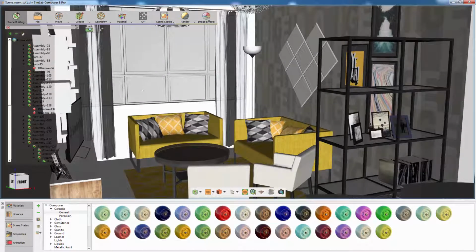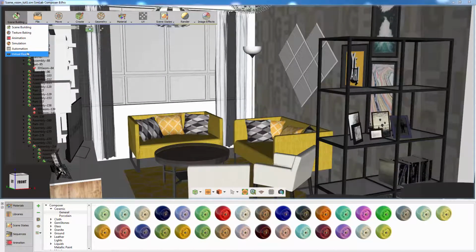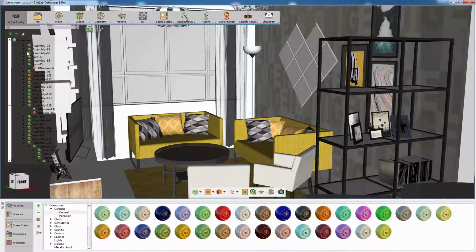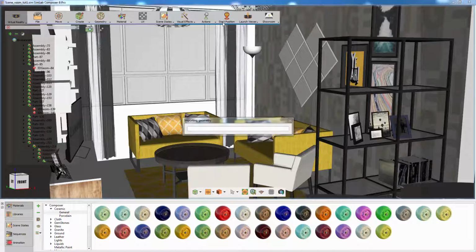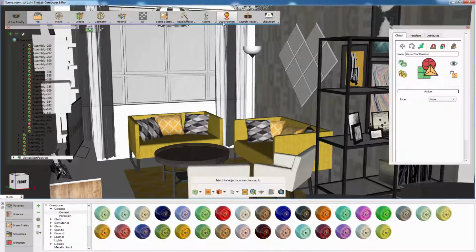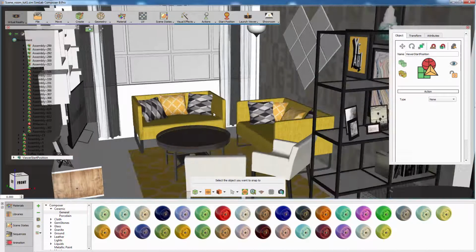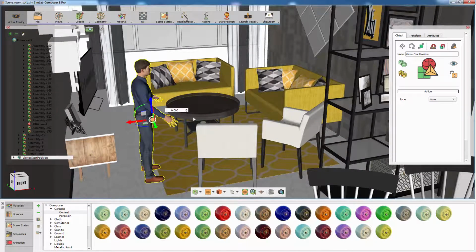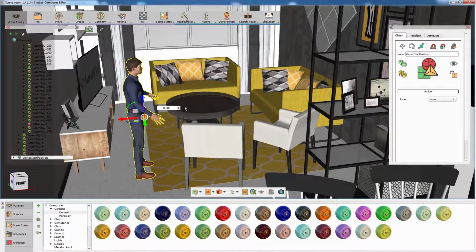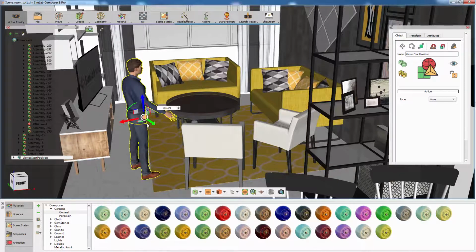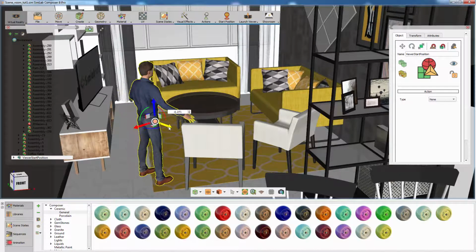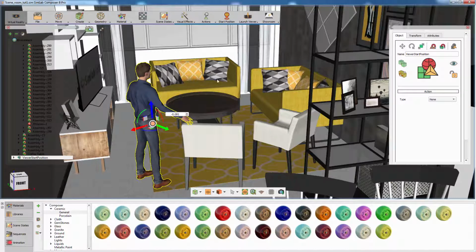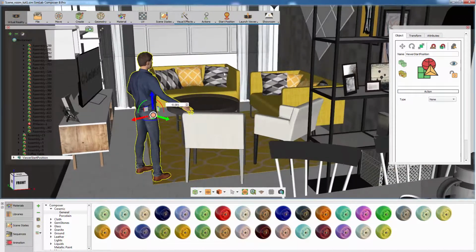Click on the workbench icon and switch to the Virtual Reality workbench. Click on Start Position. Start Position will load a human 3D model into the scene. Click anywhere on the ground to place the human model. The human model is a representative of the camera in the VR experience. Therefore, placing it somewhere specific in a certain angle will determine the starting camera in the VR session.